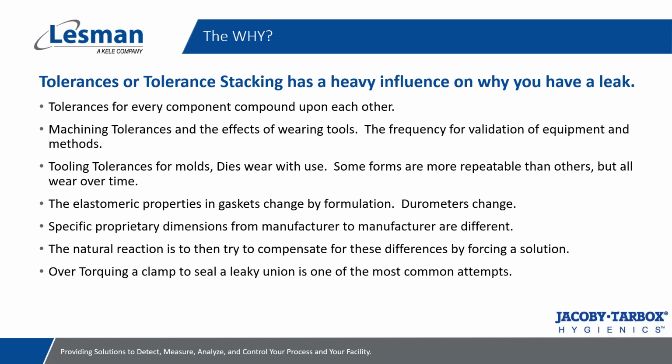There are tooling tolerances for the molds and dies that are used for the elastomers. Some forms of dies and molds are more repeatable than others, right? You've got the difference between a metal mold and a sand casted mold where they wear at different rates. They wear faster during certain manufacturing applications.